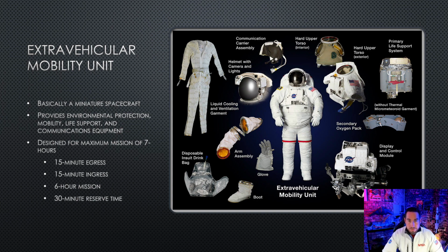The suit itself is designed for a maximum mission duration of 7 hours. This includes 15 minutes for egress. So when you're getting into the suit, getting everything turned on, pressurized, your clock starts. Then 15 minutes of ingress, of getting back into the airlock, a 6-hour mission duration, and then 30-minute reserve time.